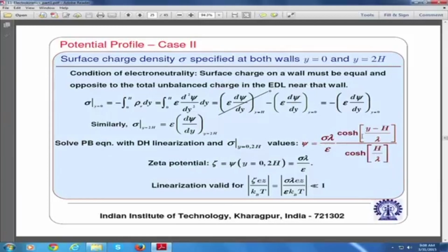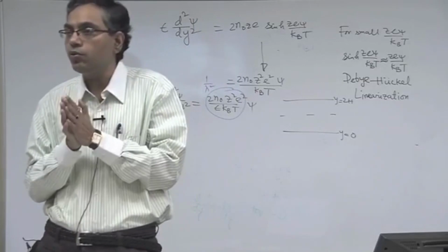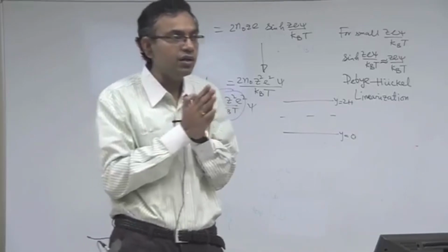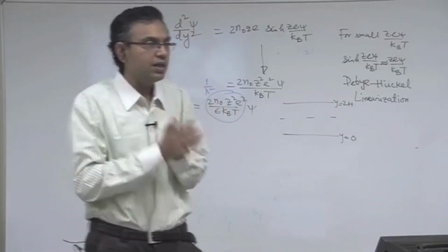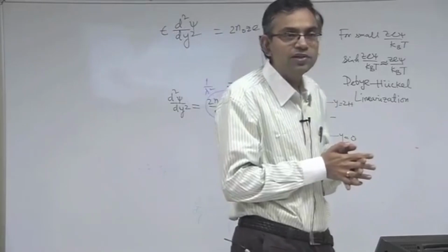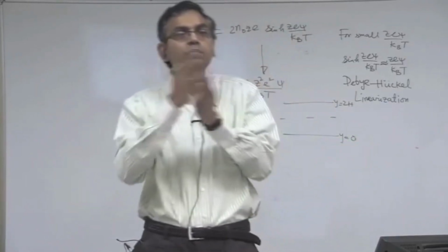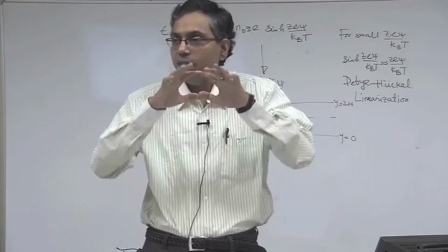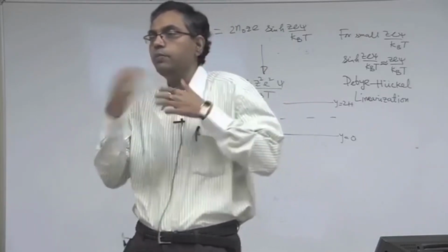See, this is the beauty of mathematics and physics. This subject is totally uncorrelated. This is electrostatics. This is totally uncorrelated with fluid mechanics and heat transfer. Look at the analogy of the boundary condition, tau is equal to mu du dy and q is equal to minus k dT dy, the Fourier's law of heat conduction and the Newton's law of viscosity. So the constitutive behaviors are so similar that you can apply the same mathematical paradigm for applying the boundary conditions.